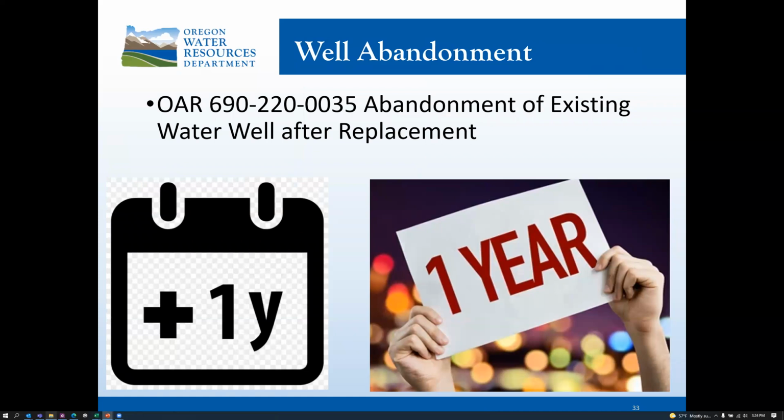So to that note, anytime a well replacement is going in for an existing well that doesn't meet applicable setbacks, that existing well is required to be permanently abandoned within 1 year after a replacement well is completed. This situation is oftentimes much better dealt with when you are on site drilling that new well than telling the landowner this information. And if there is a situation like this, please reach out to your local well inspector so that we can become aware of this non-compliant existing well and work with the landowner to get it permanently abandoned to help protect the resource.